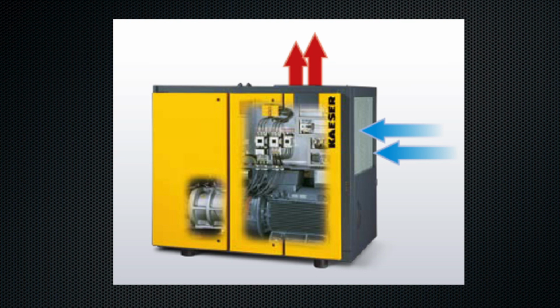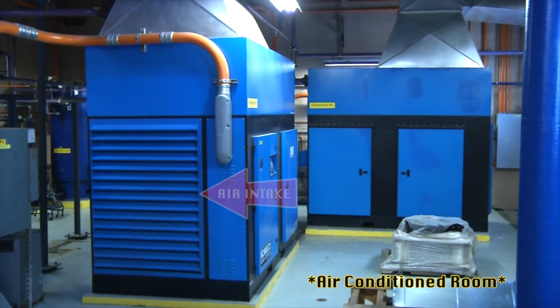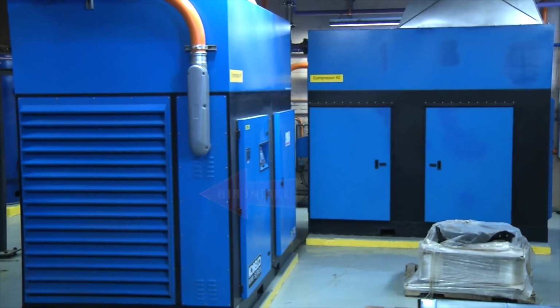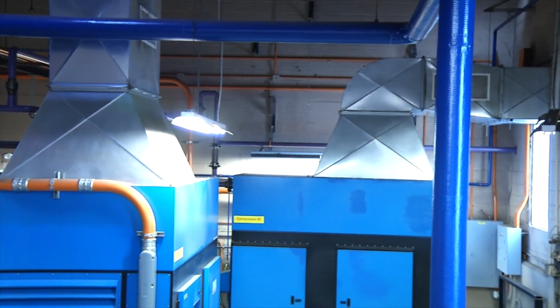Here's another idea, a common one, based on the idea that it's easier to compress denser air. Cooler air is denser, so you'd like to bring cooler air to the compressor from a cool place. If your plant is air conditioned and you have a small air compressor, during the summer you'd like to use that air conditioned air. However, in wintertime you might well bring that air in from outside. Most people will duct the intake to their air compressor from the outside.